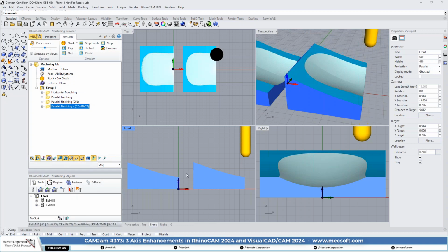Joe mentioned that everything is within tolerance. The problem with that is when a tool touches the parting line more than once, a tolerance is applied. So if you're applying a tolerance when it touches the first time, then you're applying a tolerance when it touches the second time. That's a tolerance stack, which can come out to be a violation or undercut or an overcut of the actual parting line. So if you're contacting more than twice, you can just imagine you're going back over that parting line, going back over the same point on the parting line, it degrades the parting line.